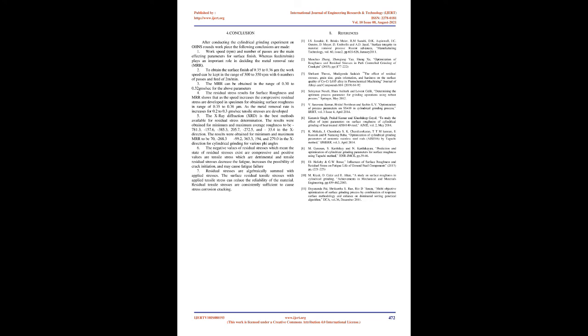The negative values of residual stresses, which mean the state of residual stresses that exist are compressive, and positive values are tensile stress, which are detrimental, and tensile residual stresses decrease the fatigue life, increase the possibility of crack initiation, and may cause fatigue failure. Residual stresses are algebraically summed with applied stresses. The surface residual tensile stresses with applied tensile stress can reduce the reliability of the material. Residual tensile stresses are consistently sufficient to cause stress corrosion cracking.